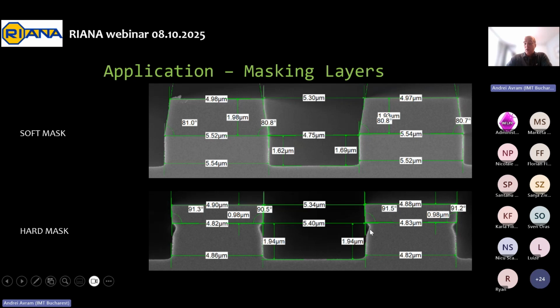And when you use the oxide, you need to compensate because, as I was telling you, you have ion bombardment, which affects the photoresist, and bits of photoresist, which are not volatile in this case, just jump off and add to your passivation here. And that's why when you use the same recipe, you get this notching, because you don't have the extra passivation of bits of photoresist flying around and redepositing on vertical substrates.